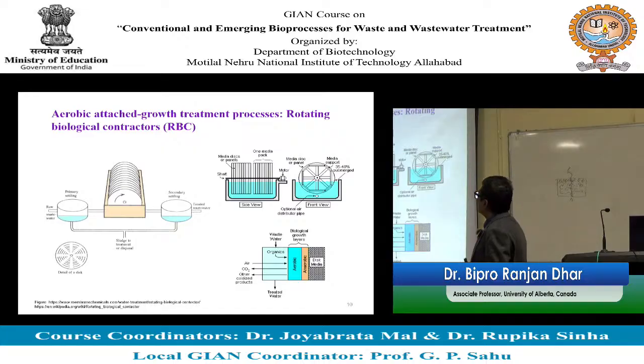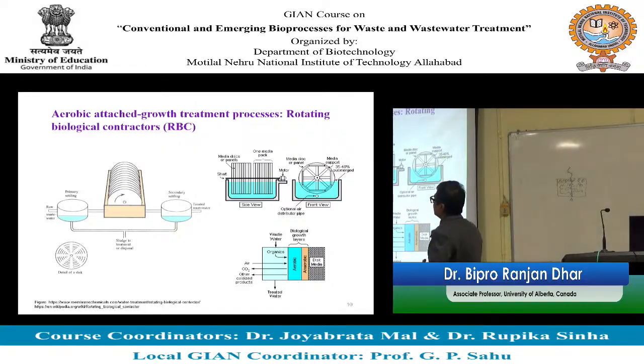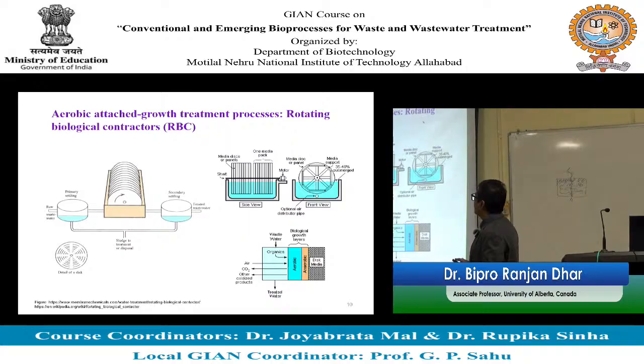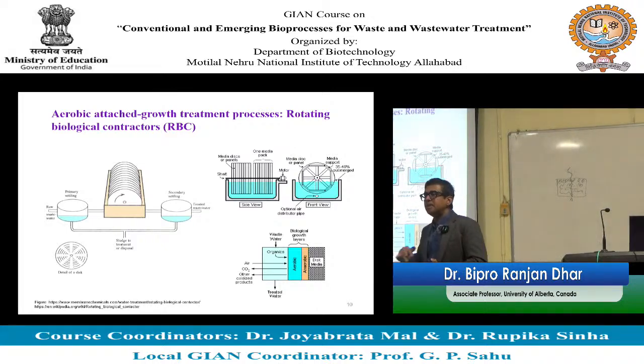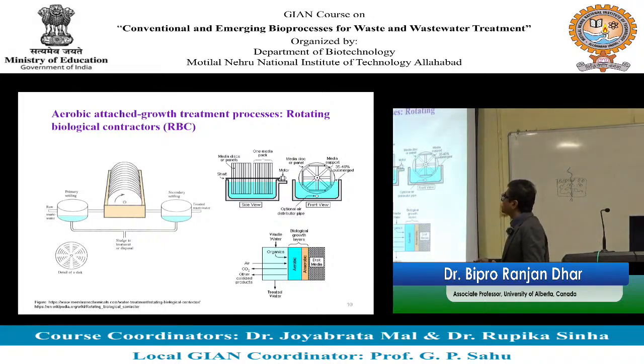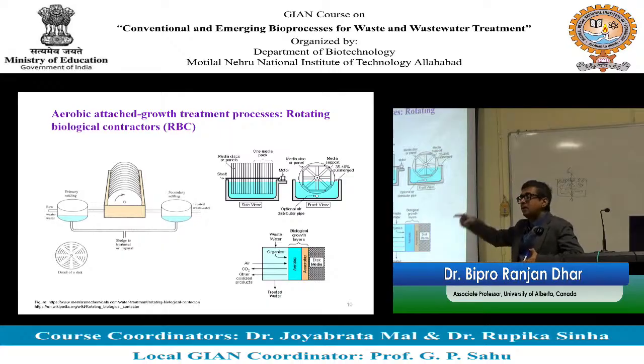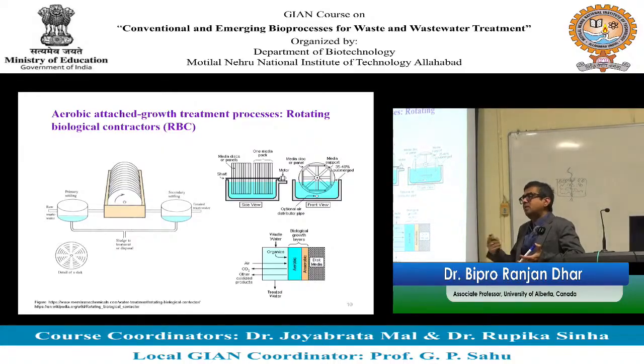Another process is called the rotating biological contactor, or RBC. You have a rotating shaft equipped with media panels, where biomass or microbes form a biofilm, and you have a shallow tank where wastewater flows through, and the media panels are continuously rotating. So you are going to have interaction. And why continuously rotating?